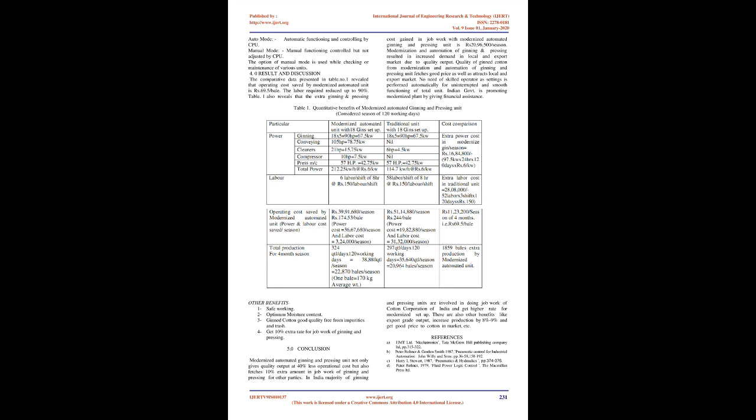The central processing unit performs operations like continuous checking and display of the status of each activity of the plant, controlling and monitoring of the conveying system, timely feeding of the desired quantity of cotton to each gin, controlling the moisture of cotton in the storage house, and judicious selection of cleaning machines on the basis of contamination level. The control panel contains all the power equipment such as circuit breakers, fuses, motor starters, thermal overload relays, etc. The automation panel is provided with auto and manual functions as below.